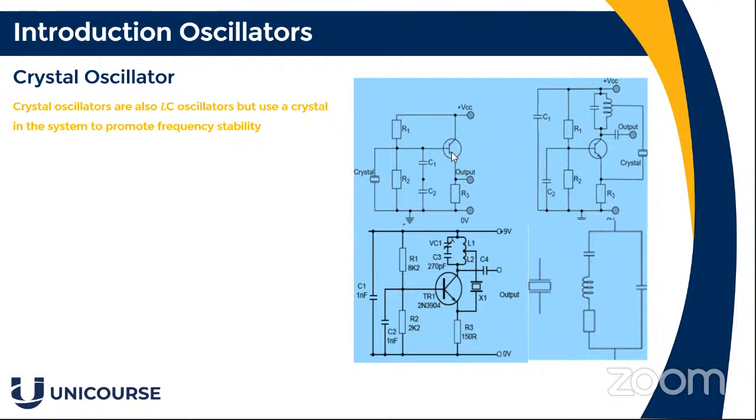Now we notice on this one, the output is not coming onto the collector, so there won't be any amplification. It'll be unity gain, but it's a bit like a buffer circuit, a common emitter stage. But as you can see here, you get a nice output. Now on this one, we've got it connected, tapped at the coil, right back to the emitter here. That's another stable circuit. And here to the right, just to give you an idea of how the circuit will look.